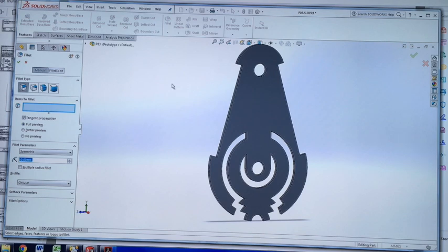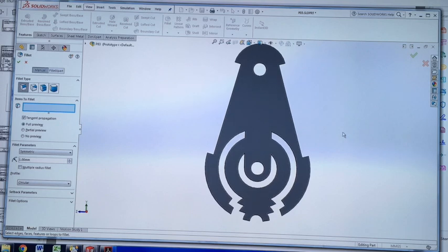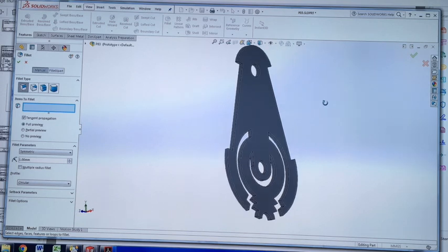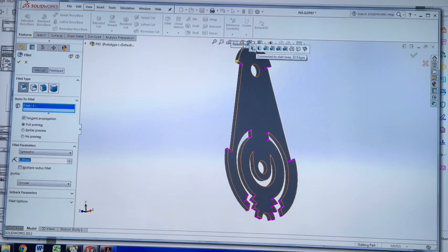Here's another trick as well with your fillets. Let's say I've now got this shape and I want to fillet all of the sharp edges. I don't have to click every single one individually. When I click one fillet edge, I get this shortcut menu come up, which shows me all the different options for that fillet. So this is connected to the start loop, which would be one of my preferred selections here. Connected to the starting face, between right feature and left feature part. So you've got all these different options that you can roll through.